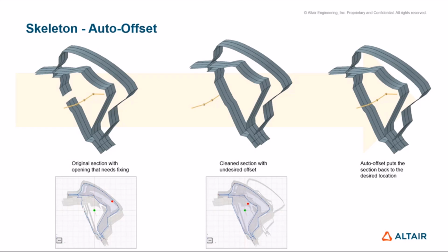We also compute the offset that is needed to be assigned to the C-beam to make the section be in the right position with respect to the midline. Here we have an example, and if I open the section in Section Manager, you can see how it looks. Please focus on the shear center position, which is important because the offset will be referenced to that position.